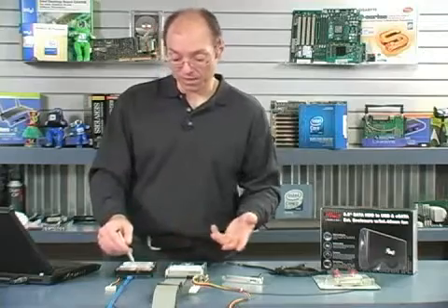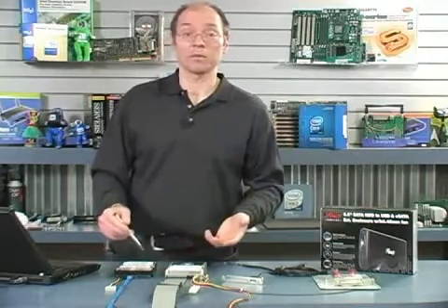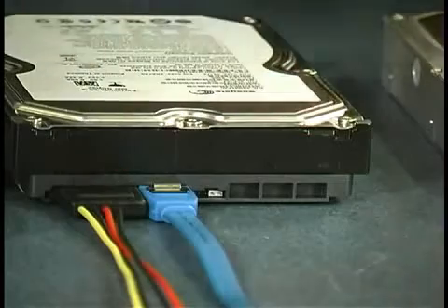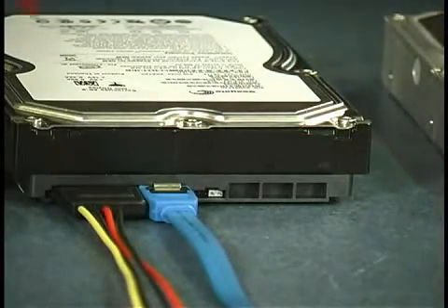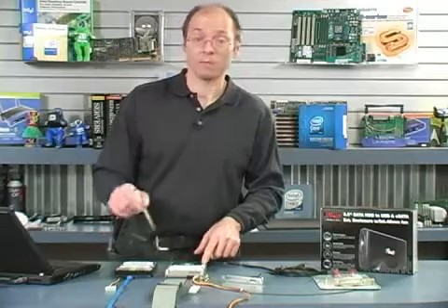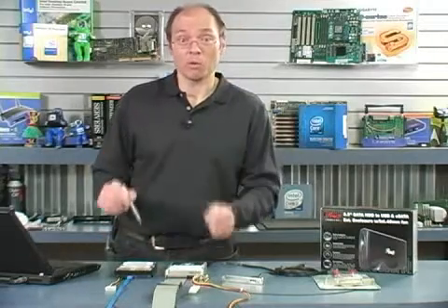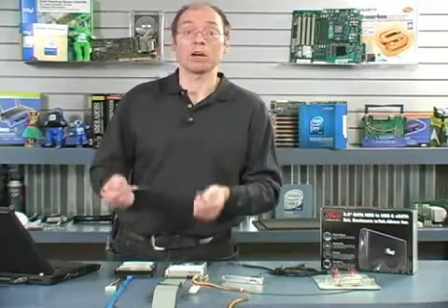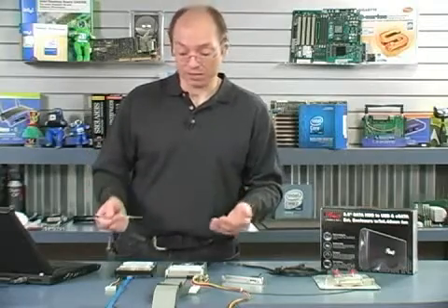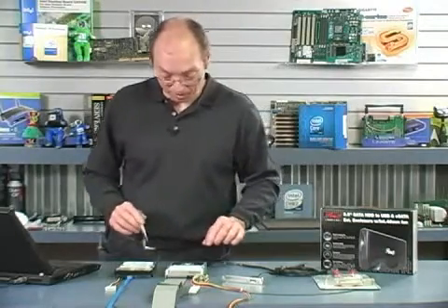I kind of liked it when they did, because oftentimes I was running into power supplies that didn't have the sufficient number of serial ATA power connectors to power all the drives I wanted to put in there. And when the drives had both, no problem. I could use the older style power connector to provide power to the drive. The important thing to note was you just can't plug 2 power connectors into one drive. That does not work. In fact, it can cause damage. So that's just a warning there.